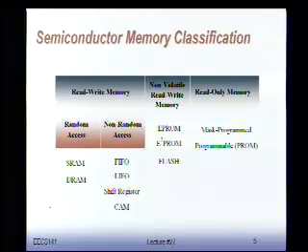That's where you store, basically, this is used as the main storage of your machine while it's running. The SRAM is used as cache. That's the fast access to the computer processor. Because there's a big difference between the two. DRAM is simpler. It only needs a capacitor and a transistor per cell, so you can put a lot more cells in a large dense area. But SRAM is faster.